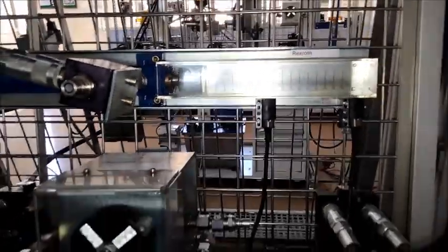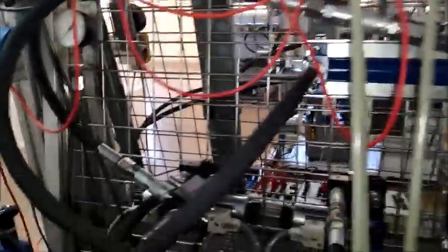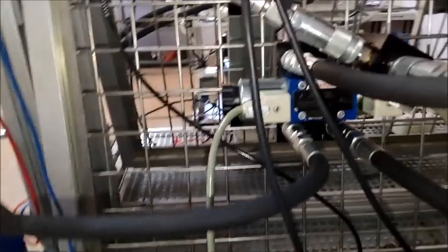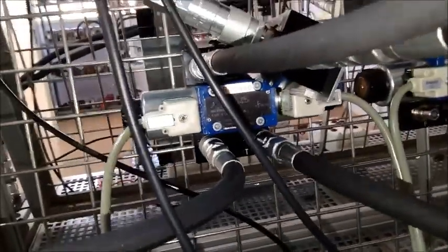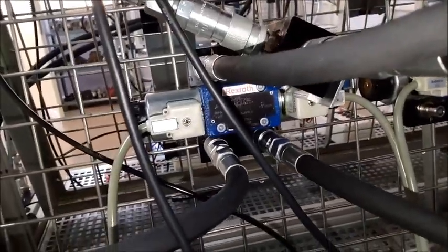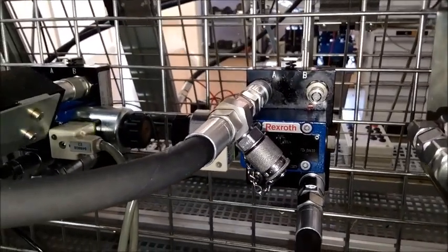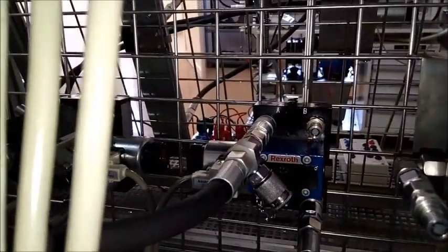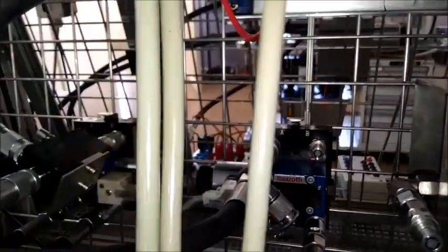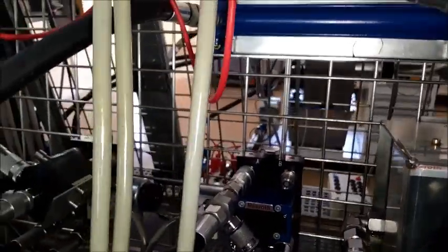So now the hydraulic circuit is designed here. The hydraulic cylinder movement is controlled by the 4x3 direction control valve, which is operated by two solenoids. To change the speed from high speed to low speed and back to high speed, we are using one more direction control valve, that is 4x2. Actually the requirement is a 3x2 direction control valve, but 3x2 is not available in the laboratory, so we are using a 4x2 direction control valve.